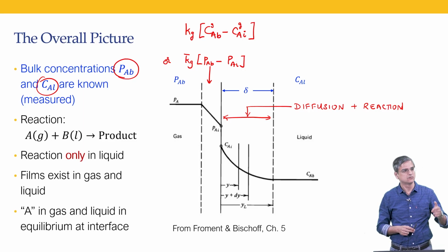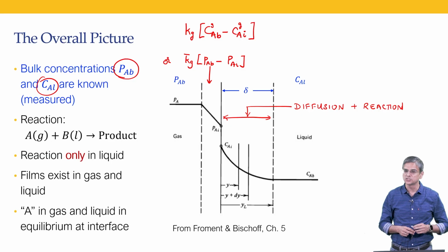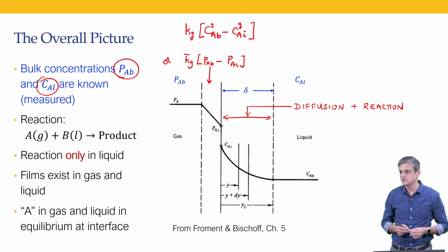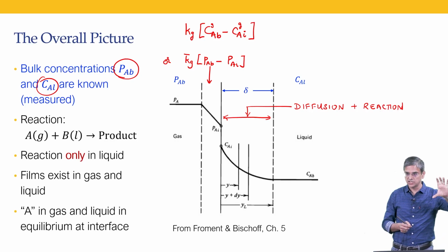Why cold? Because we want to arrest the reaction. The reaction stops as soon as it gets in touch with the cold fluid. Let us say we take 1 ml and dissolve it in 99 ml of liquid. That means whatever you measure from that liquid, you just multiply by 100, and that was the concentration originally.